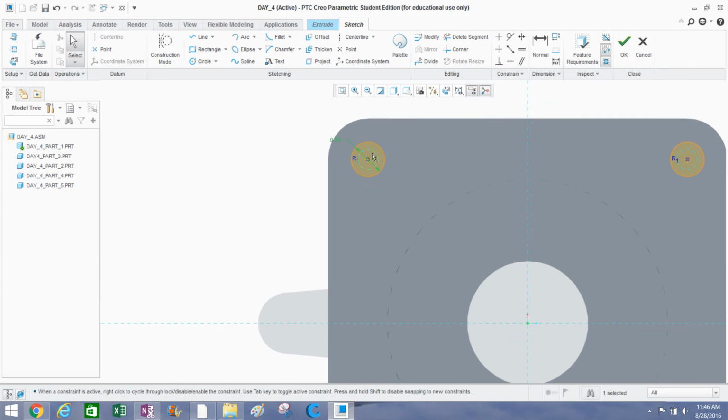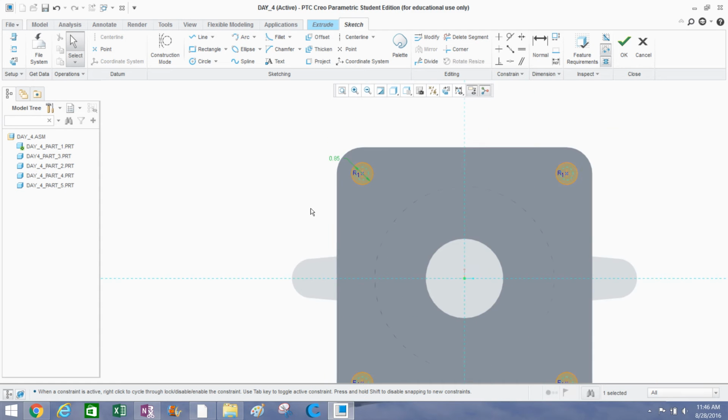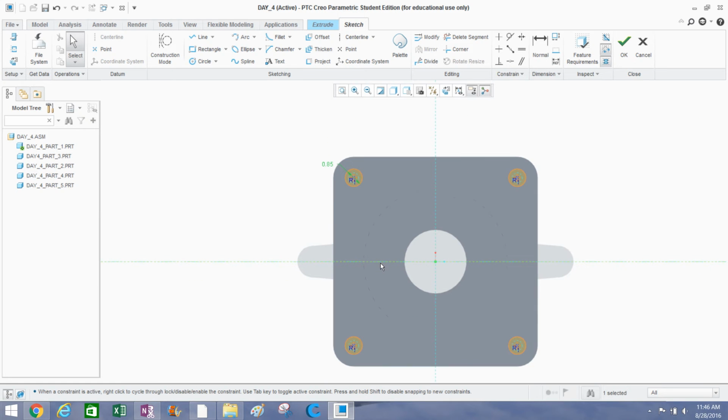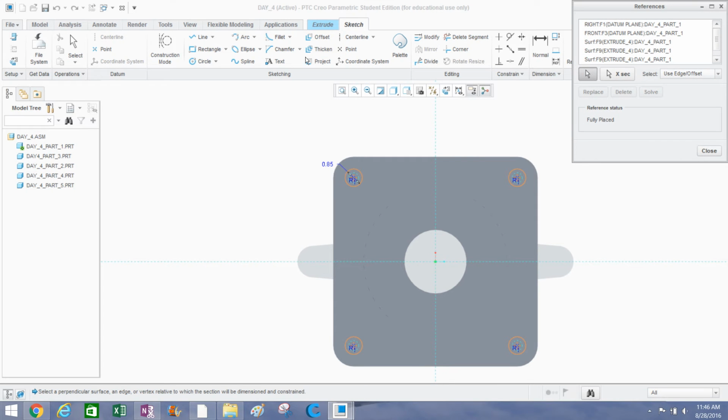And so at this point, with these 4 referenced parts, you can see we don't actually have any dimensions on this view. You will actually need to remove those references in order to be able to have the drawing fully dimensioned properly. So what you need to do is come up here to the left again to References, click on it, and we're going to come over to the right and delete the 4 references that we had there.